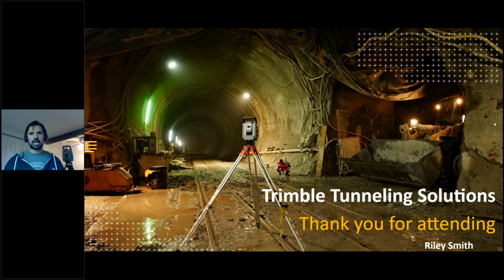And the idea behind that is you have a lot of issues on a long linear tunnel with EDM refraction, so you want to try and mitigate that with this zigzag methodology. So that's one thing you want to take into account. Line of sight is always a big thing in tunnels, so you want to consider that. With any control survey, you don't want the control to be too far apart. You don't want it to be too short as well.